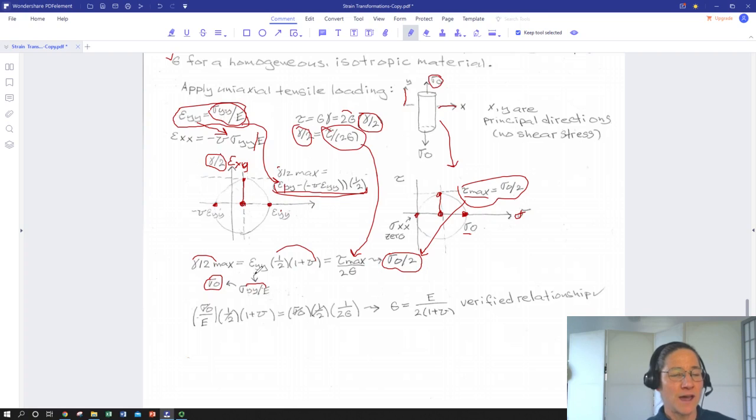So now we have some expressions that basically have the applied stress 1/2 (1 plus Poisson's ratio) equals applied stress over 2 divided by 2G. So if we write all of this in terms of just the applied stress and the elastic constants, we end up with our applied stress over E, first term, times 1/2, coming down here, 1 plus Poisson's ratio.